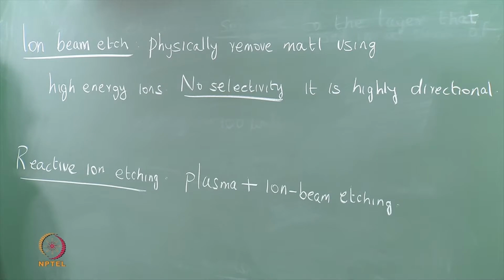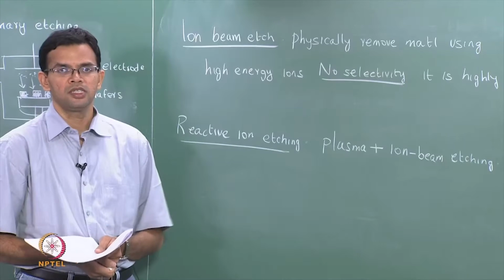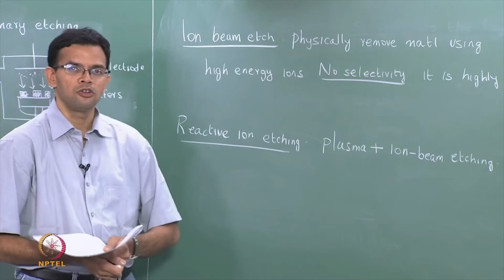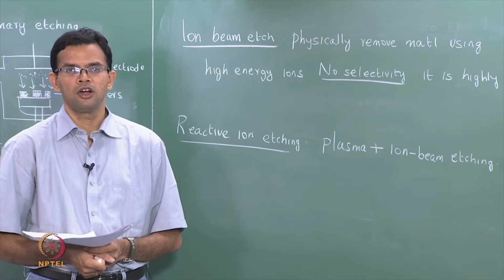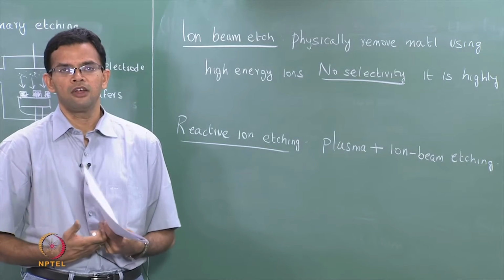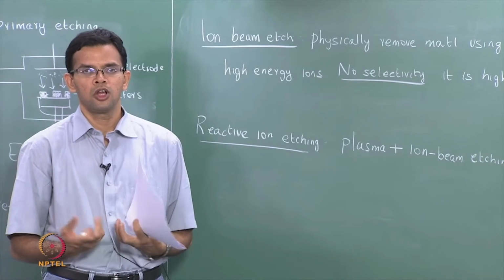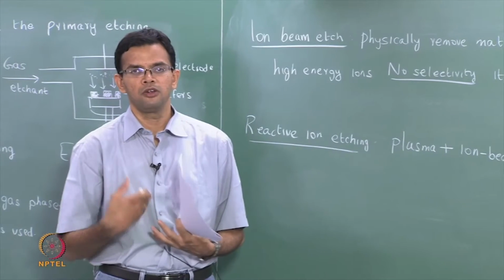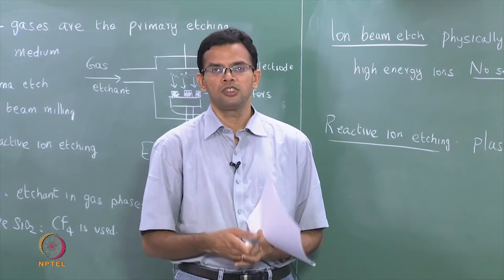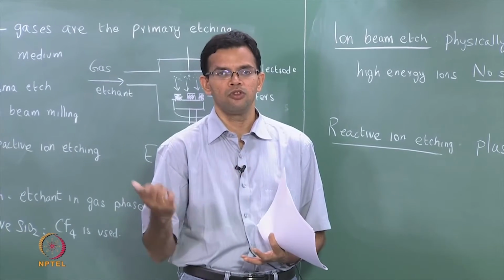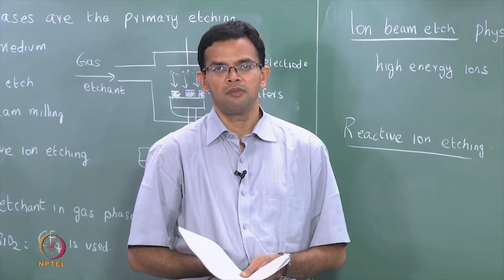Dry etching is also used to remove the photoresist after the etching or the growth process. Again, we saw in the last class when we did lithography, we spun a layer of photoresist on the surface, opened some windows where you can do some work or some chemistry on the wafer, and after the process is done, we completely remove the photoresist from the entire material.